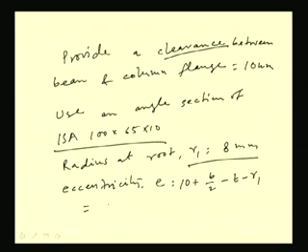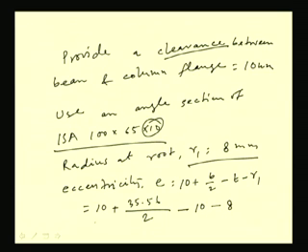So if we calculate, this will become 10 plus 35.56, the bearing length calculated as 35.56, by 2, minus thickness of the angle that is 10, minus R1 found from SP6 as 8. After calculation we are getting 9.78 millimeter. So the eccentricity we are getting is 9.78 millimeter.